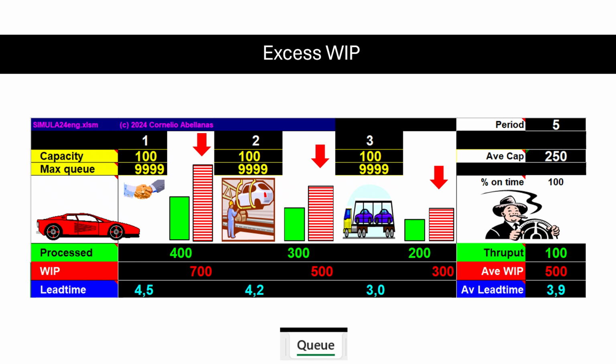Another way to eliminate the excess inventory in the line is to apply just-in-time. This consists basically in banning the accumulation of inventory by decree. The way to do that is to work in pull mode. You only produce if there is empty place to put your output.